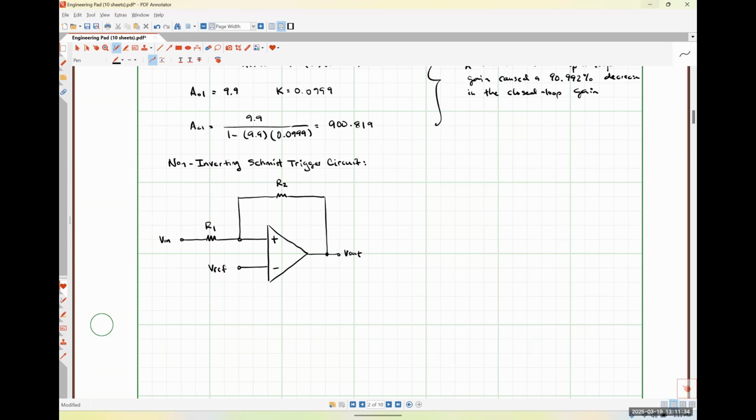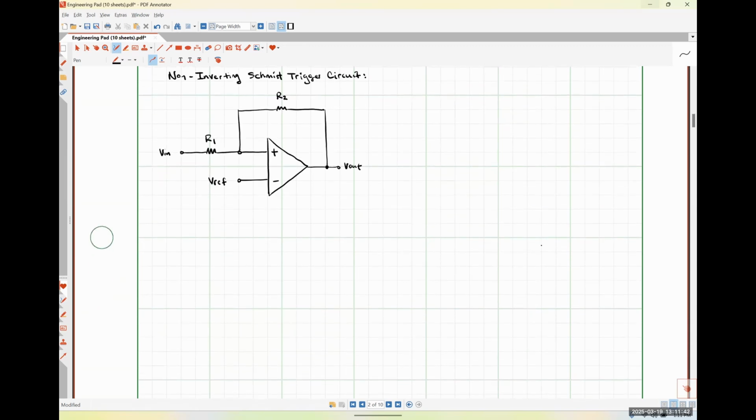Okay. So in order for us to analyze this guy and figure out what's going on, we're going to need to use that practical op-amp model that we introduced a couple of class meetings ago, right? So for my practical op-amp model representation of this guy, I'm going to start with just the op-amp model itself. So here's my input resistance, Rn. I'm going to say that this terminal up here is my non-inverting input node. This terminal down here is my inverting input node. And so that makes this my differential voltage, VD.